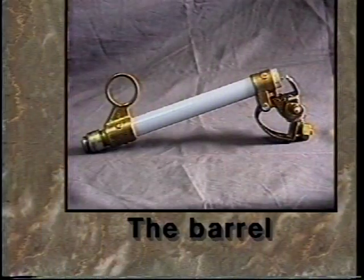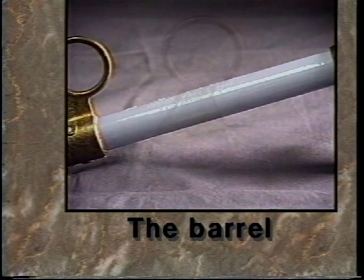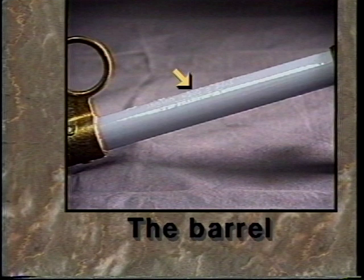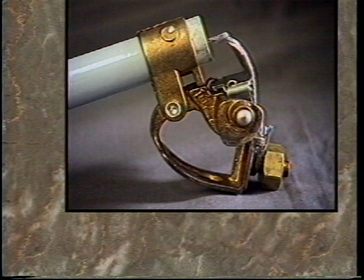The barrel. One end of the cutout barrel consists of a contact cap and an eye for opening and closing with a hot stick. A vulcanized rubber tube covered with fiberglass joins this with the other end, which contains hinged contact points, a fuse tensioner, a nut to secure the tail of the fuse to the bottom terminal, and another eye for installing the barrel in the cutout.